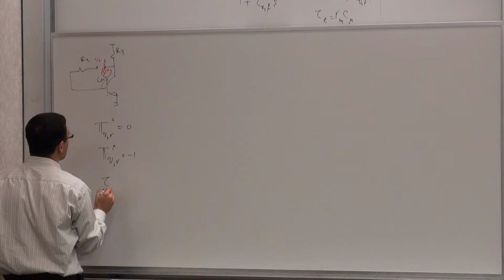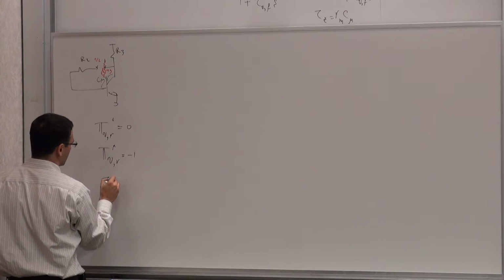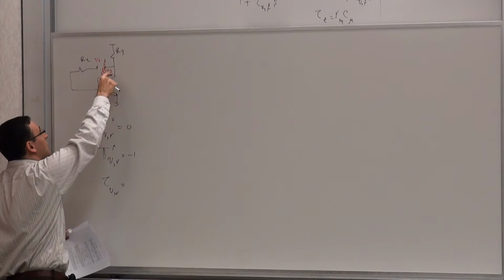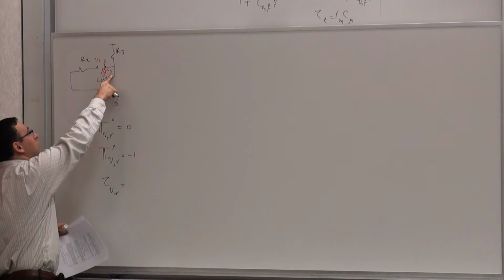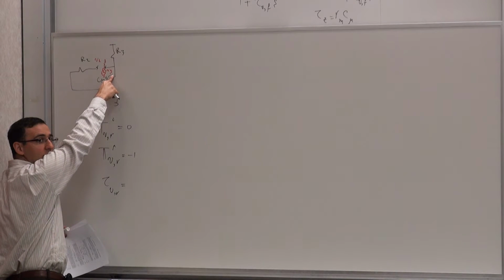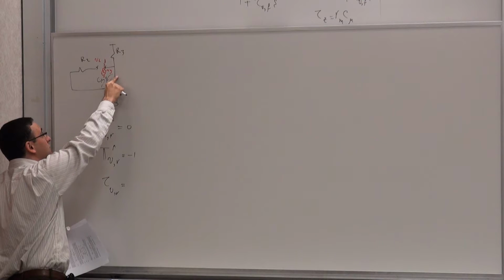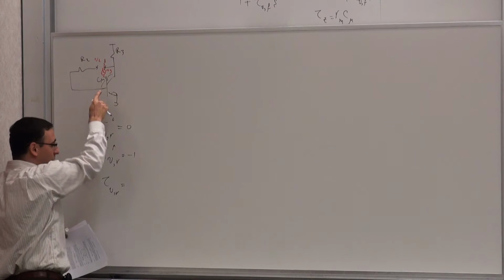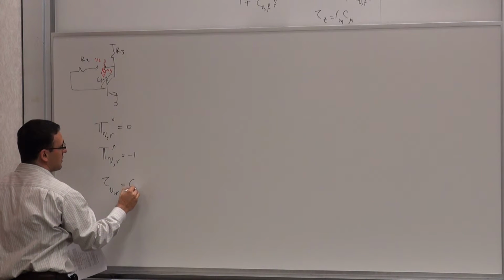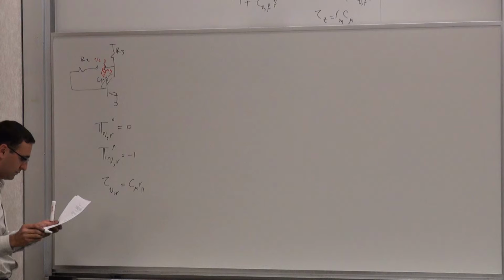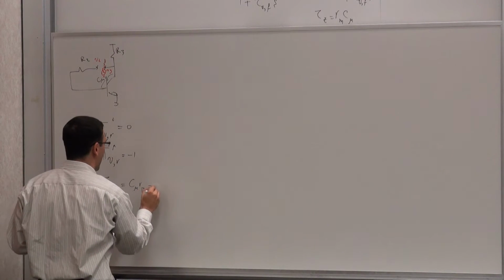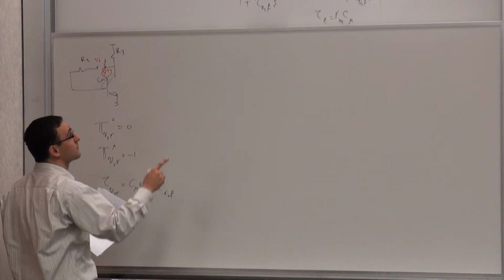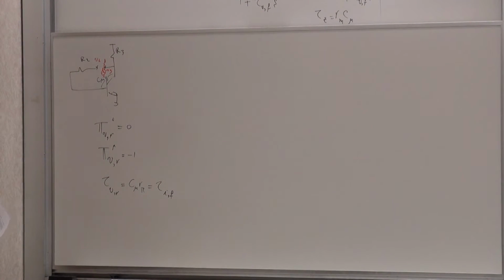And there's a time constant, tau_Br, which is what? This is the voltage source. And the resistance seen by this guy, so it's shorted on this end, because it's the source. The voltage source, when nulled, is going to short this to ground. This side, what resistance do you see from this node to ground? R_pi. So it's C_mu R_pi, which is equal to tau_IF. Right? Okay.